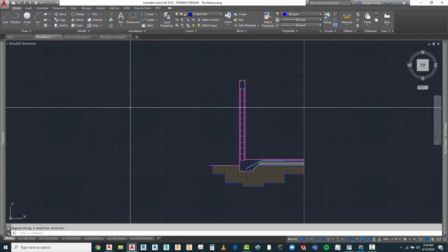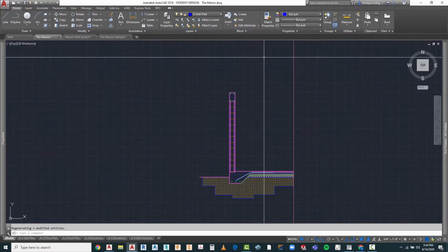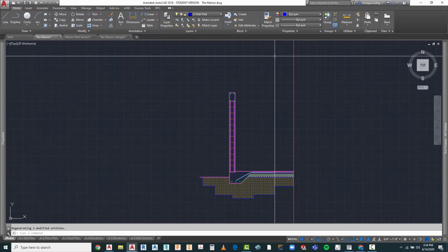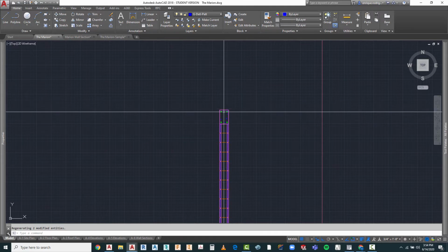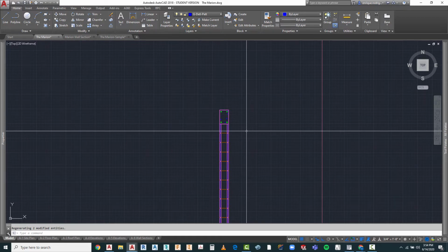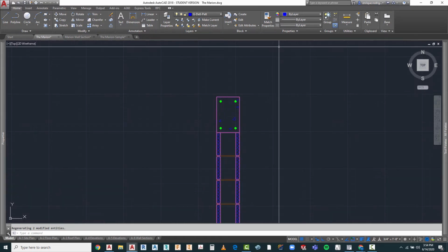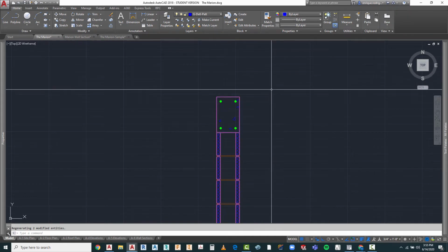So the next thing that we do, before we add our roof rafters, the roof rafters are the framing members that will rest on the wall and support your tile and your plywood sheeting, etc. When you do your rafters, you don't want those rafters touching the concrete.